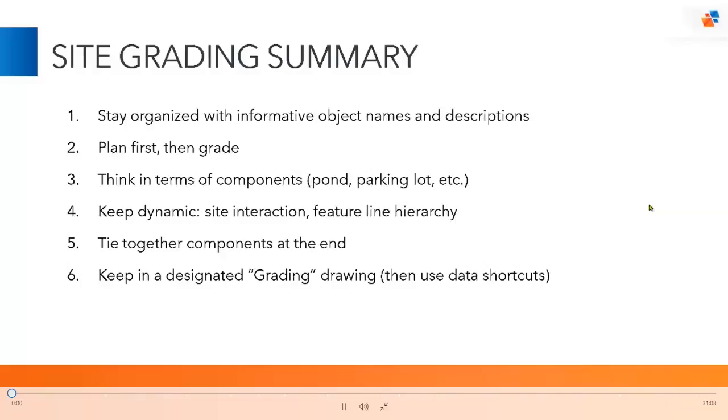And I didn't really mention this too much, but we really want to make sure that we're keeping our grading scenarios separate. You'll notice that your project grading is going to make your drawings a lot larger. So I would recommend that you build out all of your grading scenarios in a separate drawing and then data shortcut that into the rest of your project design. With all of these concepts in mind, I hope you found this webinar useful. At this point, I'd like to turn things back over to Ramil to wrap things up.